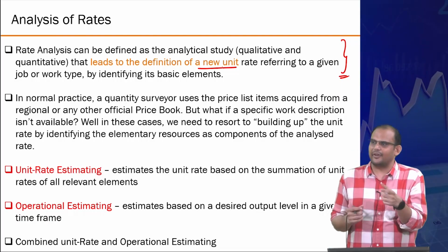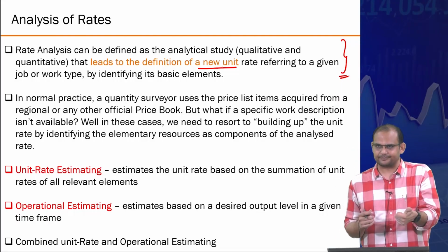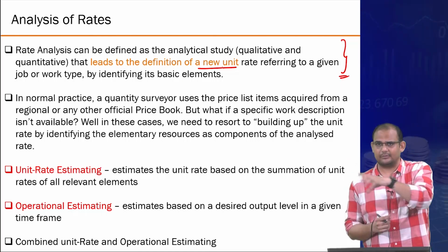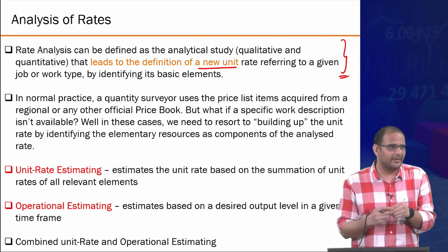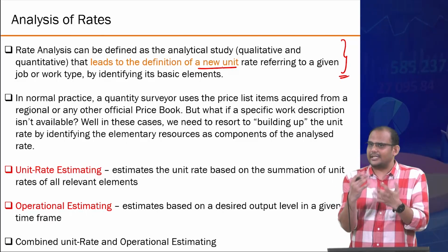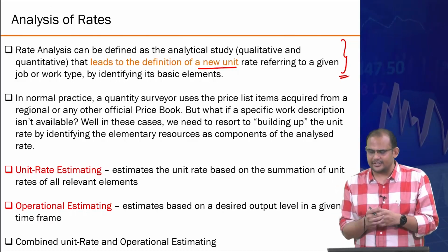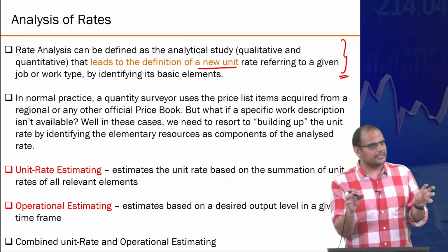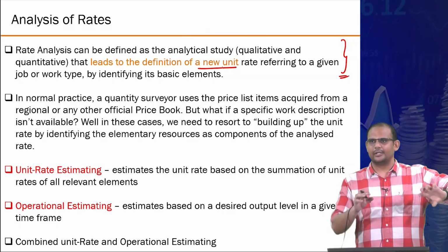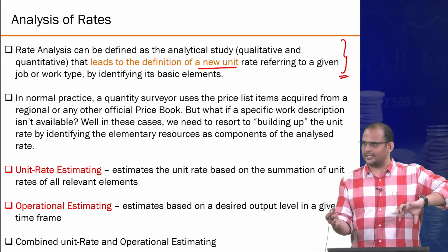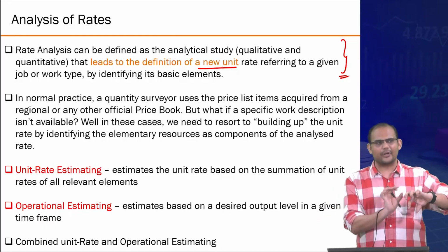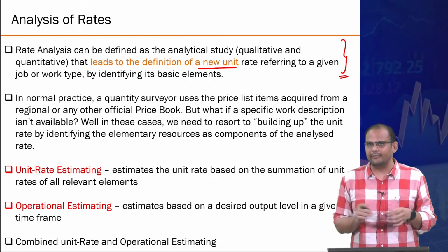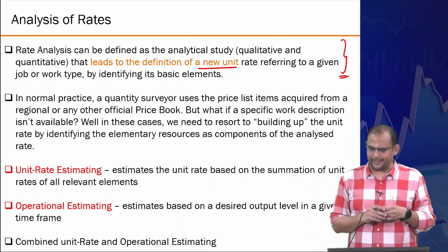Brickwork, sometimes you define as the actual number of bricks, or you could define it by surface area also, because the depth of the brick remains the same. So it's tricky, keeps on changing, right? But the idea is you define the activities, you define a unit, you calculate the total number of units, you estimate the cost for each unit, and you aggregate to get the total cost that we need to estimate, right?